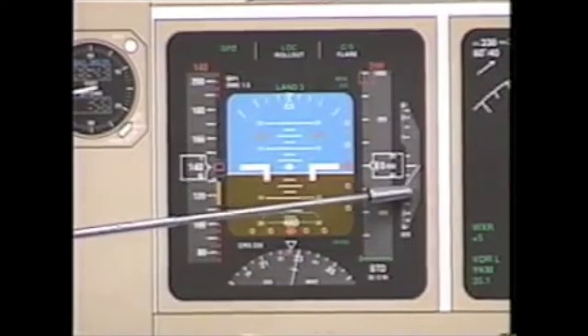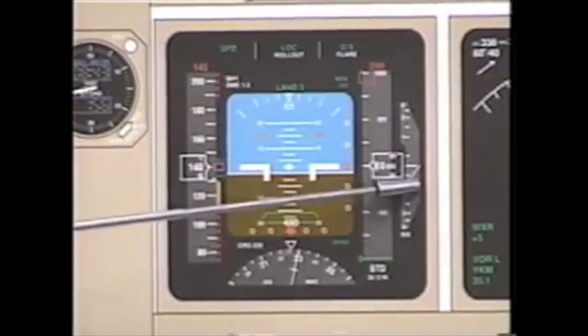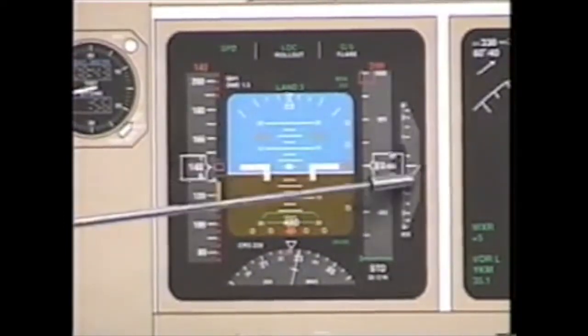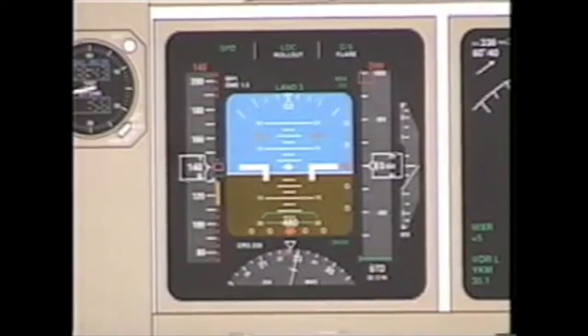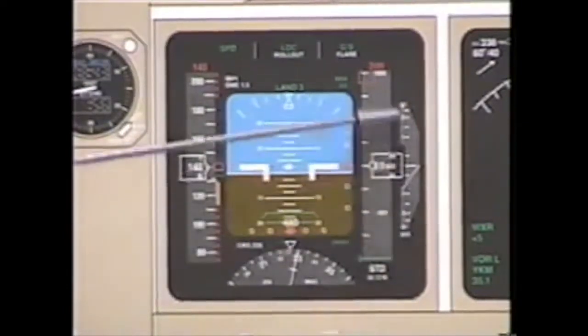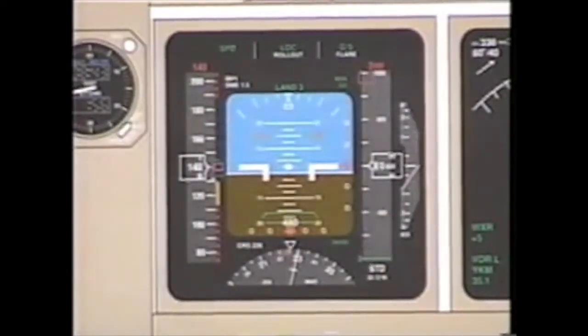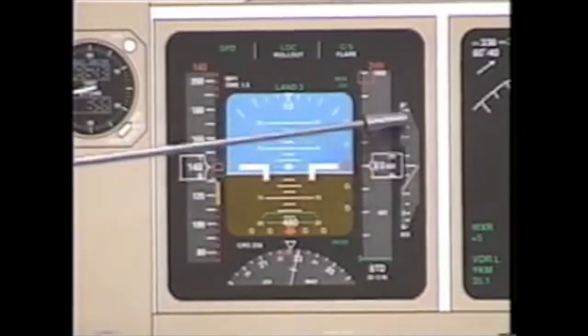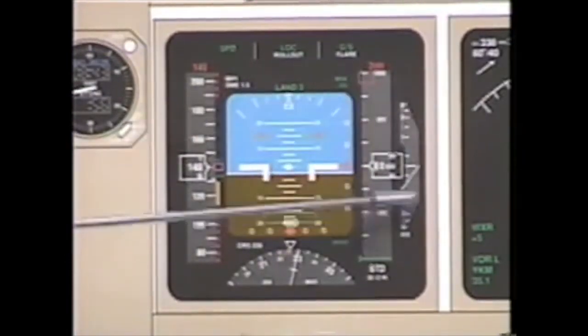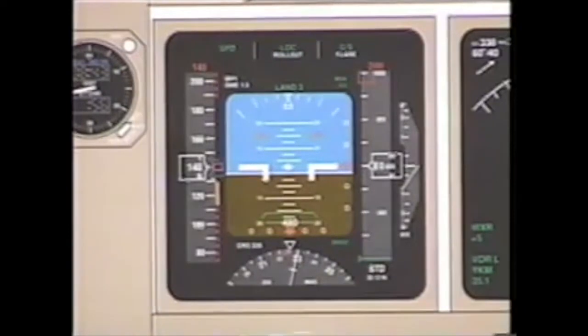Vertical speed comes from the accelerometer of your IRS. Anytime you climb or descend in excess of 400 feet per minute, you pick up the descent or ascent rate specific. So anytime more than 400 feet up or down, you pick up the specific, in this case, descending at 850 feet a minute.